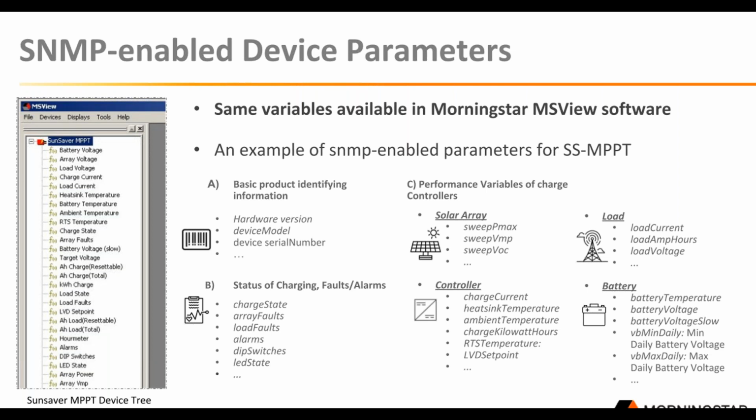And again, you can see, in terms of how you configure your monitoring template, you could have all of the OIDs related to solar data, on the array side, in one section of your template. You could have all of the parameters related to load data in a different section, all of the battery parameters, all the temperature parameters. They can all be segmented so that the data display is a little bit more consistent and straightforward for the user.